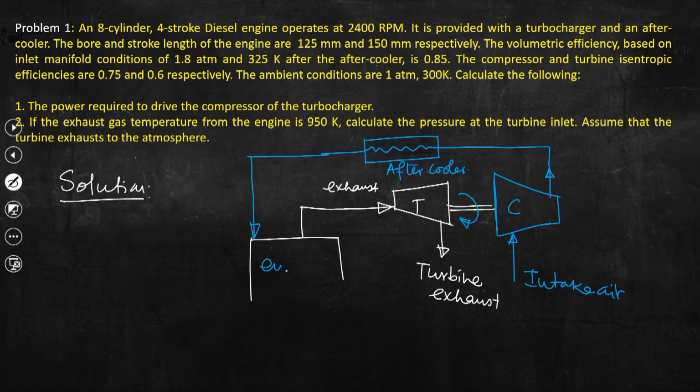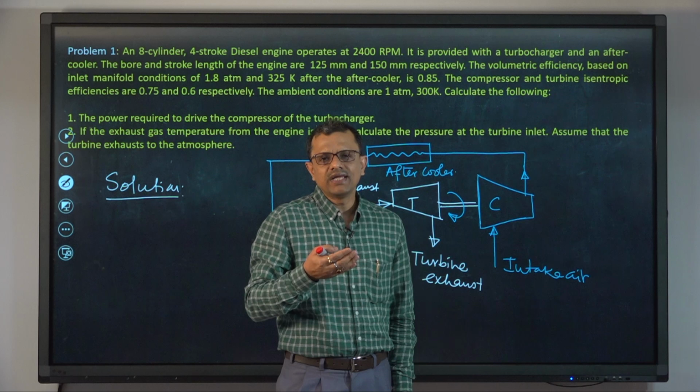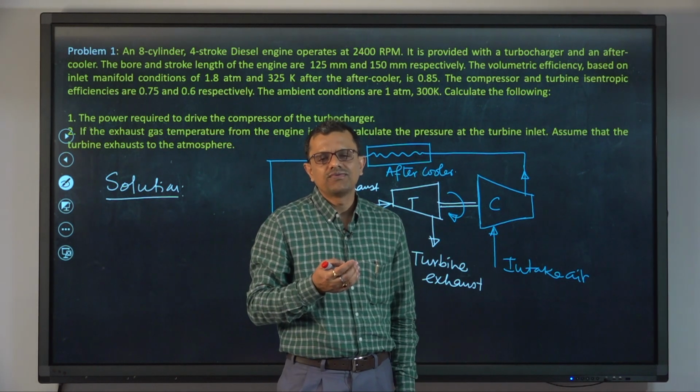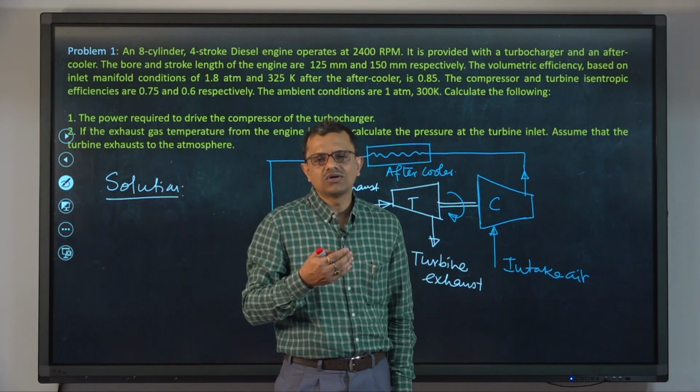So, this is the engine, and if the temperature of intake air is higher before it enters the engine, its temperature will rise further and it will create some operational issues for the SI engines, because it will create knock or detonation.